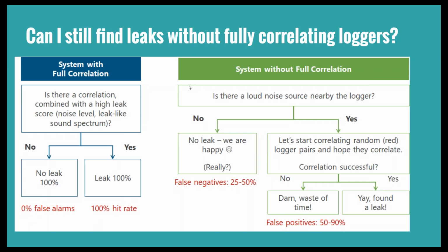So can you do leak detection with just the basic correlators and just ground sounding? Absolutely, but the best bang for your buck is, even when we go out and do some surveys, even if it is just one specific area that a client wants to look at, setting 5 or 6 loggers makes me feel better because we can collect more data and verify exactly where that leak is with multiple correlators working in unison all at once. Go ahead, Noah.